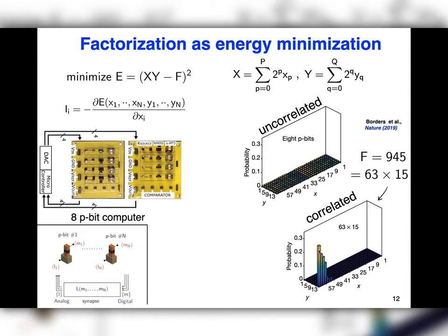Okay, so this is a probabilistic system. So in order for you to measure something, you need to take some time average, and it really gets you to the right answer. So this was just a generic demonstration of how the thermal noise in the MTJ is turned into some useful computation. And the key idea is how cheaply it comes. You really harvested the intrinsic noise in the system without ever running a random number generator or anything like that.